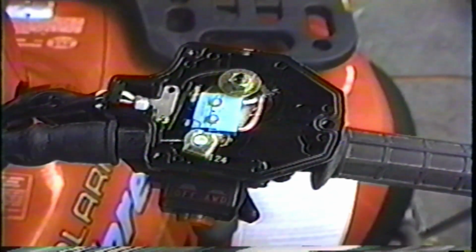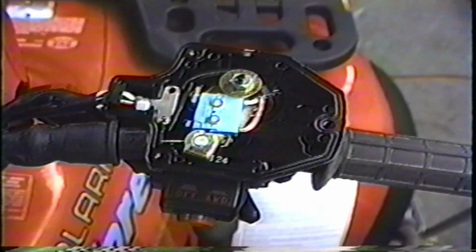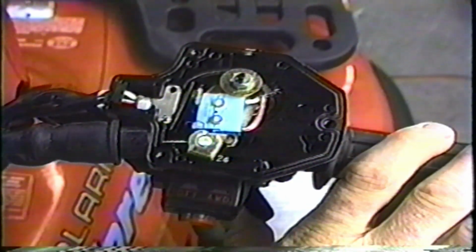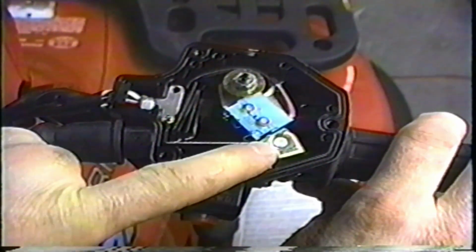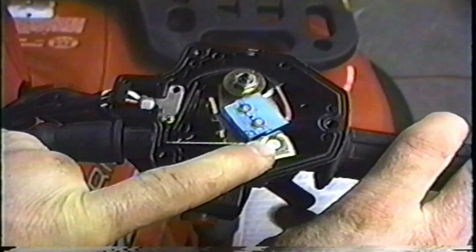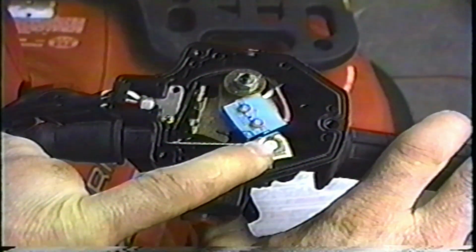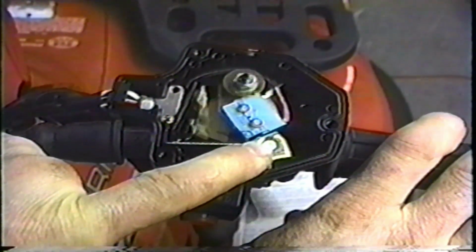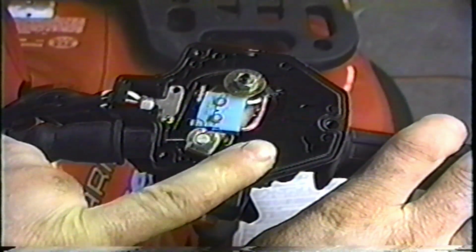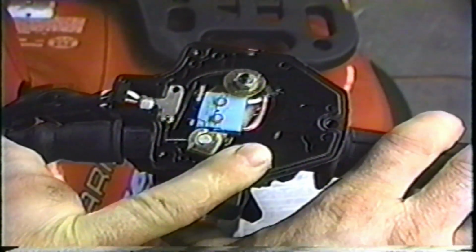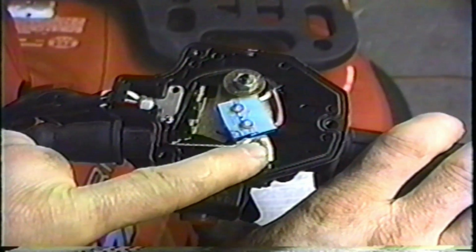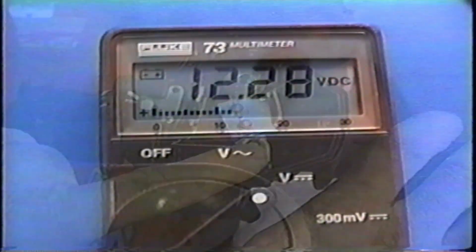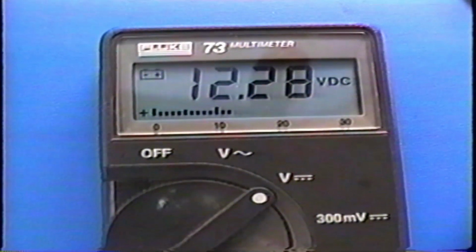On 1994 and newer ATVs, the ETC switch is attached to a spring-loaded lever. The only time the ETC switch provides power to the speed limiter is when the throttle valve is held in the open position and the driver lets off the throttle flipper. During normal operation, the ETC switch button should be depressed all the time by the throttle cable tension. When the switch is open, internal contacts are closed and battery voltage is provided to the white wire going to the speed limiter module.